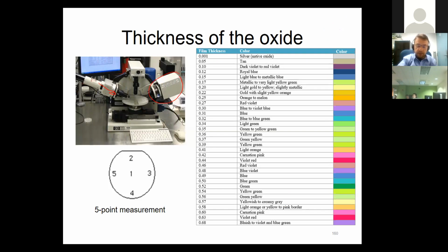Based on the reflection from the laser to the photodetector, we try to understand reflection from the wafer sitting in the center. That wafer, based on its characteristics, the thermally grown oxide or thermally grown nitride on it, will alter the properties of the reflected light,